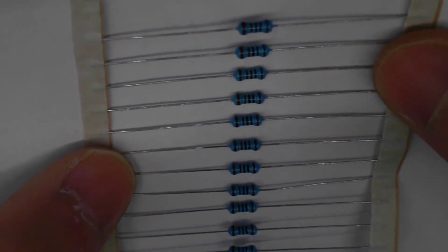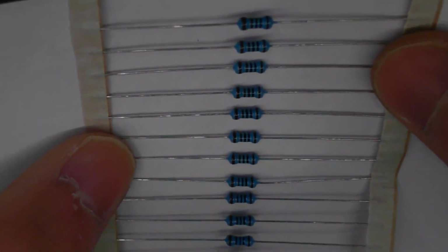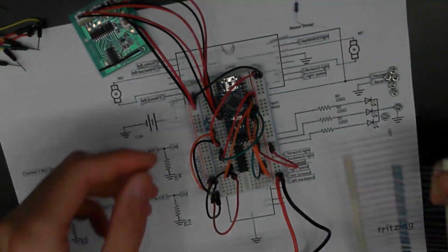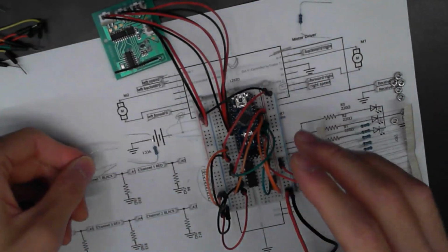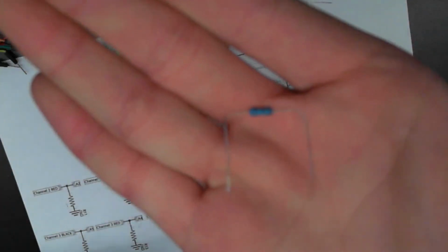And they only came in 4s, so if you have a pack of 6, you know that's the right one. So again, the color ordering for this one should be brown, black, black, then brown, if you're reading it from this orientation. And these are all 1Ks. So, to connect them to your board, I recommend bending them into this staple shape.